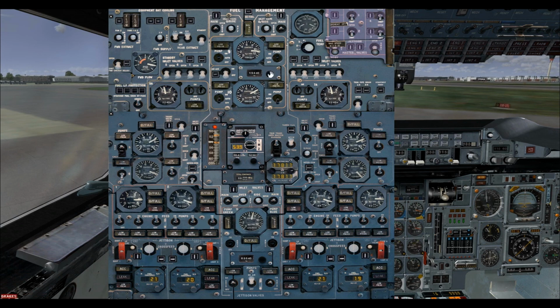and we're getting there now. This is obviously a huge pain, but you want to know how to fix it. This is how you fix it. So then all of a sudden your load limit controller is high enough, and you can see fuel's now moving back into tank 9, and this CG will start to come down. Probably a good idea to just stop here until you've got this sorted before you continue to taxi.